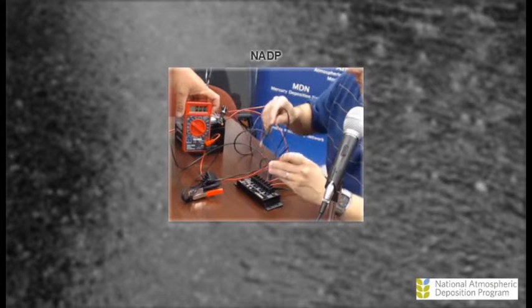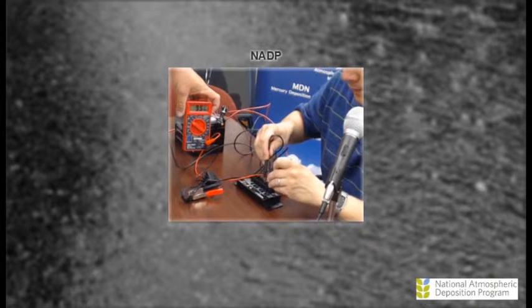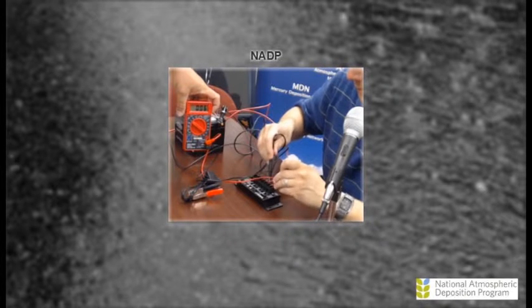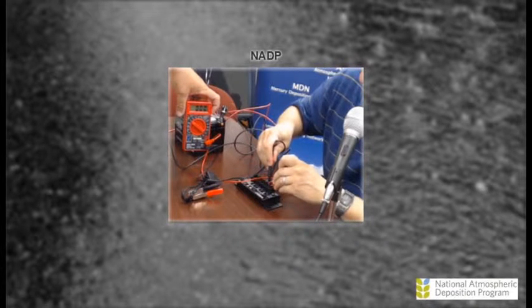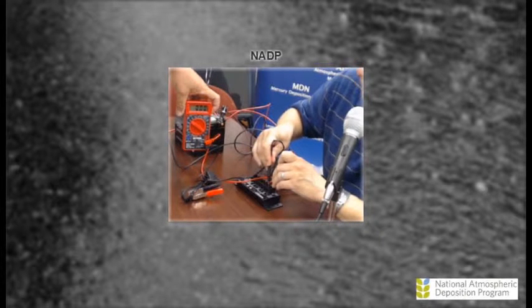That's coming through. We will also get 13 volts at the regulator where it's hooked in, but we can see out to the solar panel it's 0. So that tells us that the blocking diode is working successfully. It's preventing the reverse flow of power.